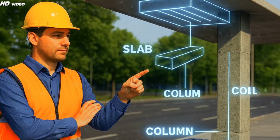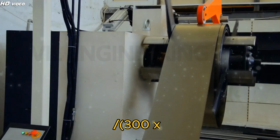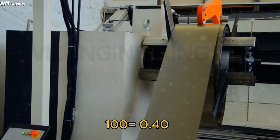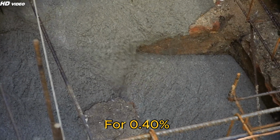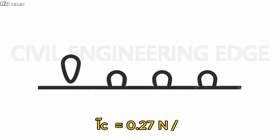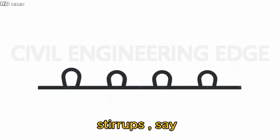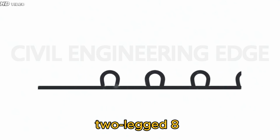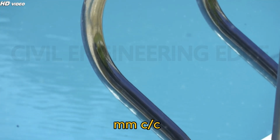Percentage of tensile steel provided equals 4 by 201 over 300 by 667 x 100 equals 0.40%. For 0.40% steel, stress in concrete tau c equals 0.7 Newton per millimeter squared. Provide nominal stirrups, say 2-legged 8 millimeters dia stirrups at 400 millimeters cc.